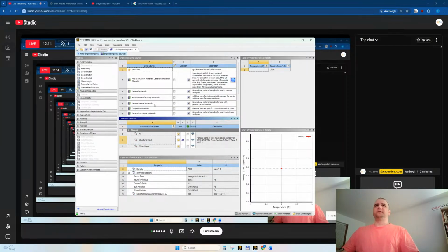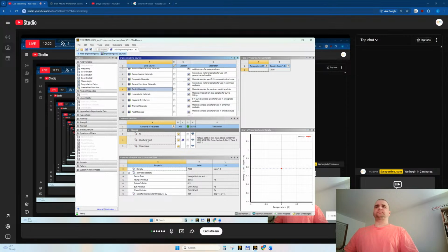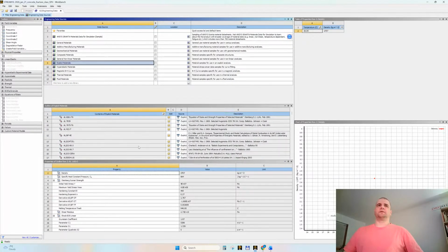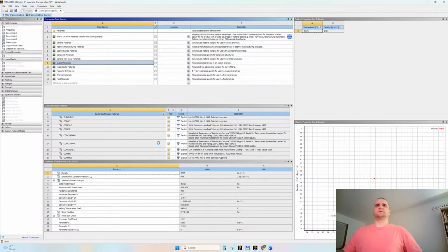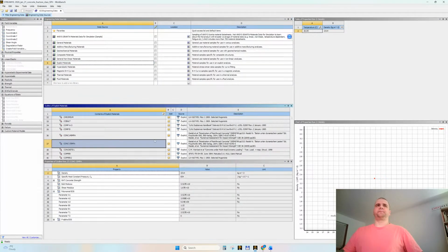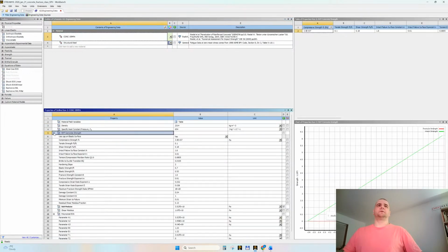And here, from the explicit materials library, we will add, it's loading the materials. We will add here concrete. There are, of course, various types of concrete. Let's choose a weaker one. I think this one at 35 megapascals. Add to engineering data. Look here, all right? So it's defined with RHT concrete strength.